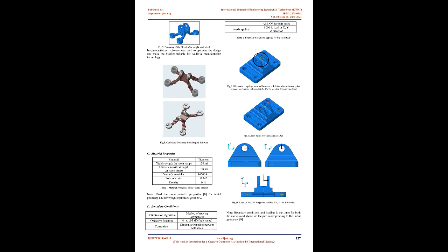D. Boundary conditions, optimization algorithm, objective function, constraints, method of moving asymptotes, default value, kinematic coupling between bolt holes. Fig. 11. Load of 8000 lbf is applied in global X, Y, and Z direction. Note: boundary conditions and loading are the same for both the models, and above are the pictures corresponding to the initial geometry.